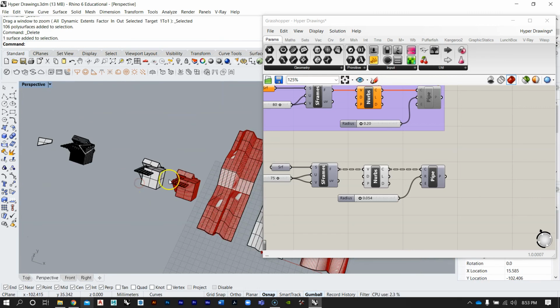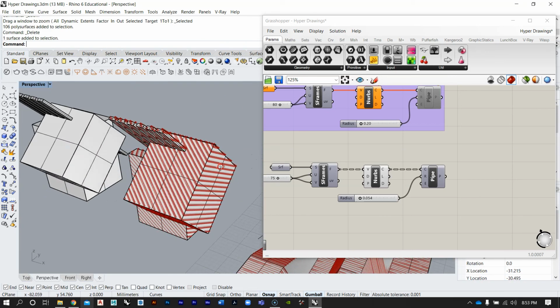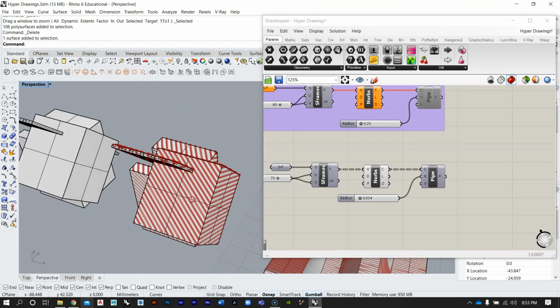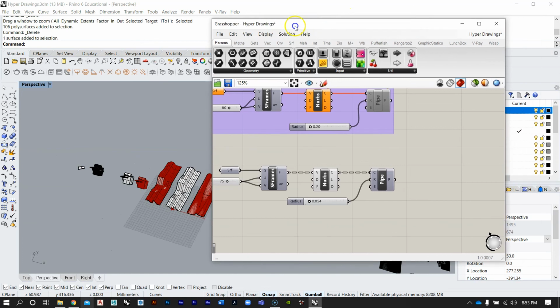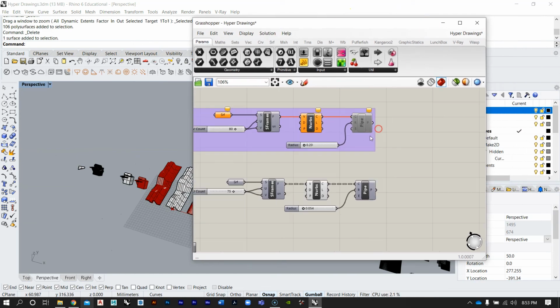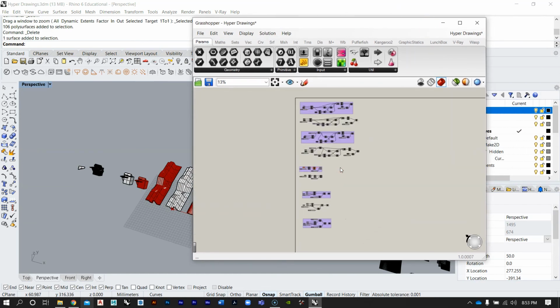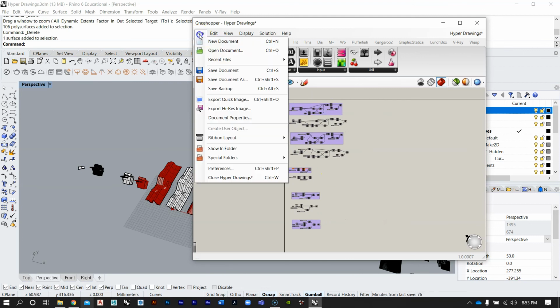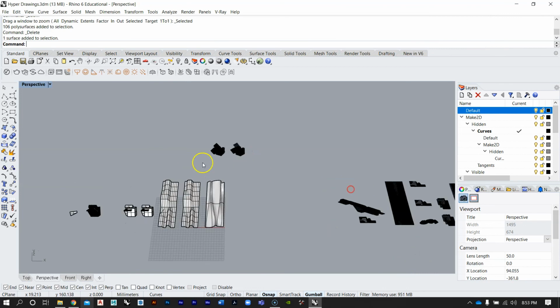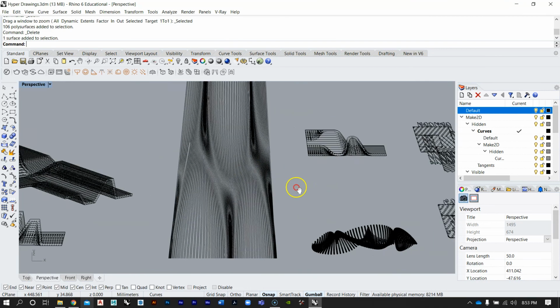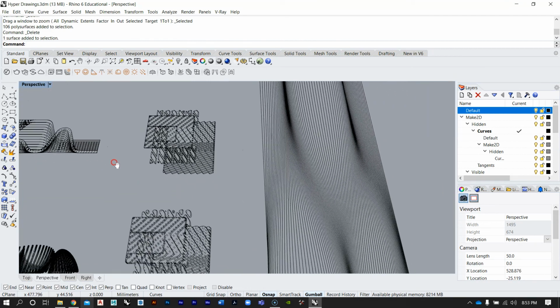And then a third way is by contouring massing models or three-dimensional models at different angles to produce those kinds of effects. All of which can be used in a Make 2D command, so you can produce flat two-dimensional images, which will allow you to produce imagery like this.